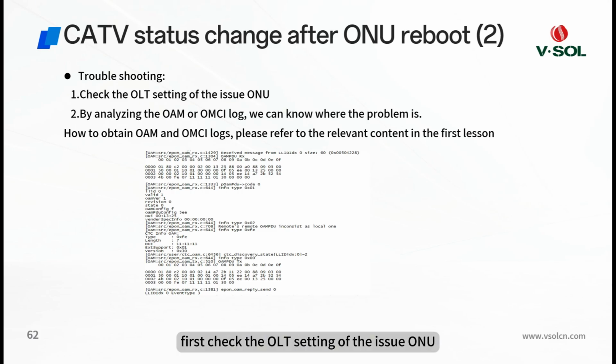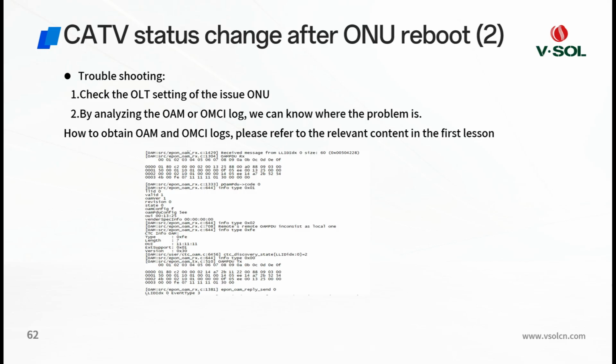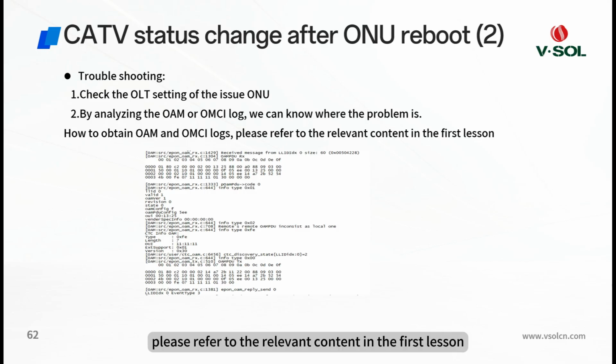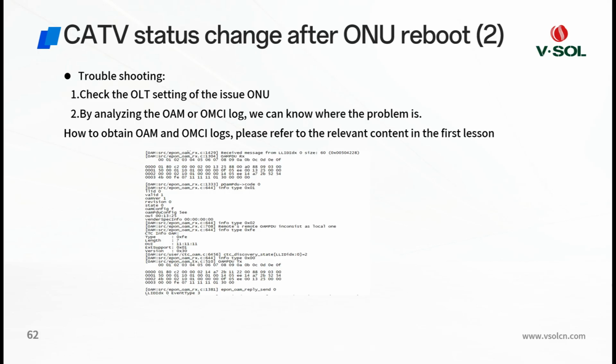First, check the OLT setting of the issue ONU. If you do not find a setting issue, you can collect and analyze the OAM or OMCI log. Please refer to the relevant content in the first lesson.